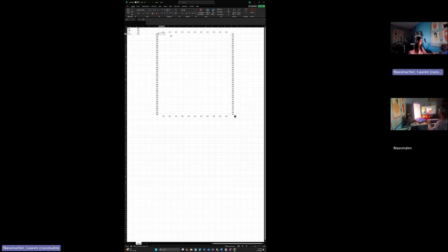Using the equation that we just derived, we know that our temperature in this position of the grid is equivalent to our temperature to the right plus, and we should also consider that we're going to divide it by 4 eventually, so put that in parentheses, our temperature to our right added to our temperature to the left, added to the temperature above, added to the temperature below, and divide that entire expression by 4. Now, if we drag this down,